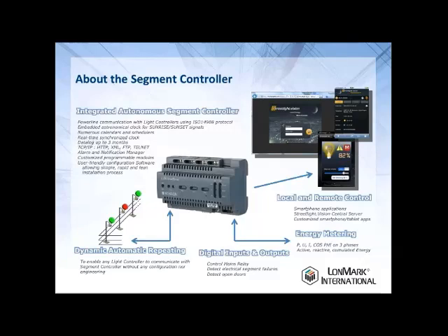Typically in Europe and in Asia, most of the streetlight networks are organized with a streetlight cabinet and between 50 to whatever 200 light points behind that cabinet. That segment controller controls both the cabinet as well as the light point controllers on the power line network. It provides digital inputs. It provides digital outputs to control the relay. It provides also some internal software to